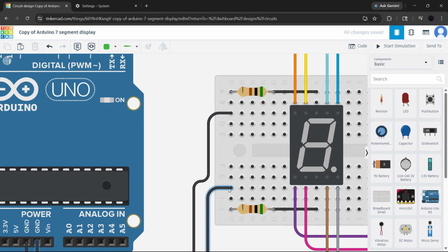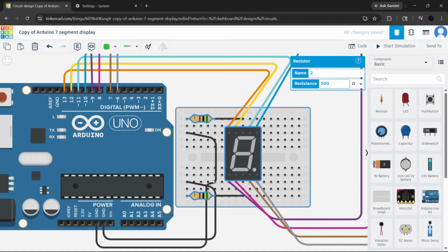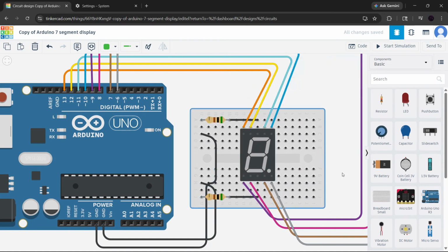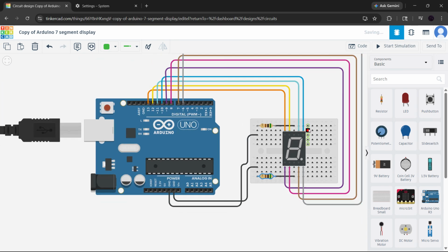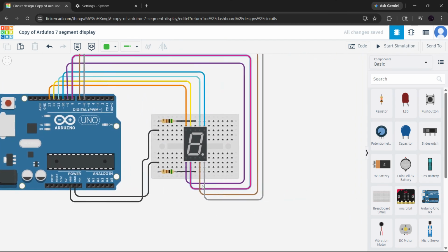Also check for something called breadboard bridging. This happens when a component like an LED or resistor is placed in the wrong position and accidentally connects the same vertical column on the breadboard. If that happens, you create a zero resistance path, which can break the simulation. So always double check the placement of every wire and component on the breadboard.